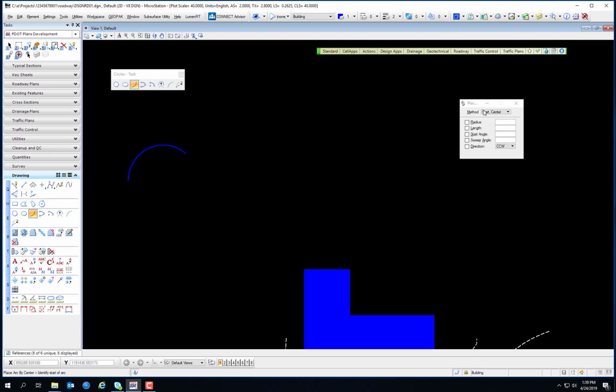and then it allows you to set the angle of the arc. Center start works the other way. We're moving out from the center to the radius, the edge, and then doing the same thing, setting the angle there. Start, middle, end is the outside to the middle of the arc itself. And you see it has this line here that functions a little bit like that edge method for drawing the circle. It gives you a lot of control there.